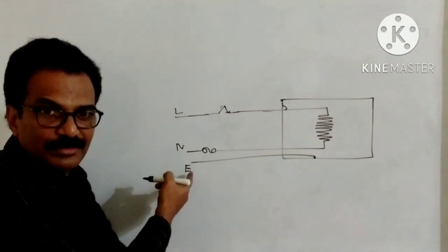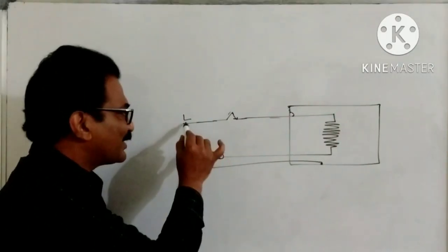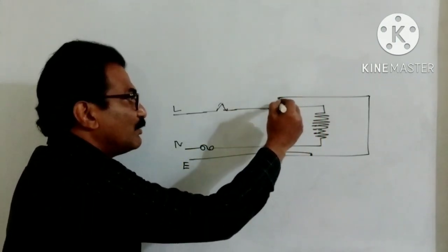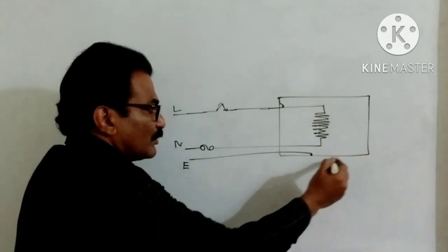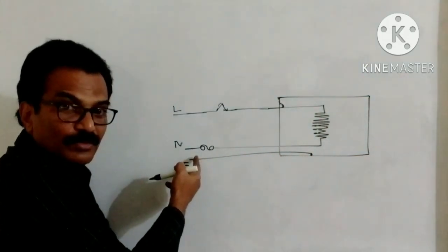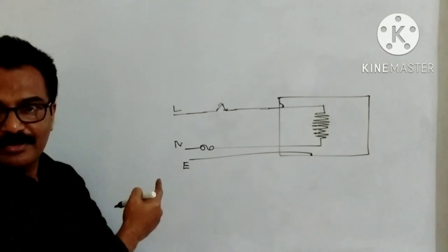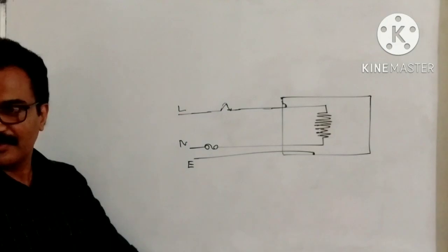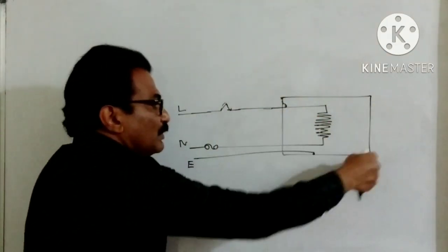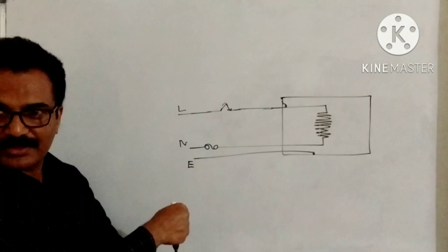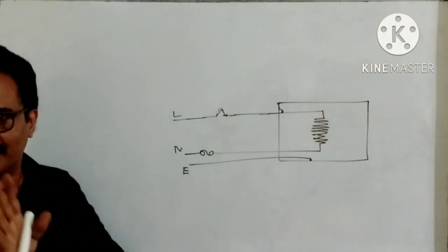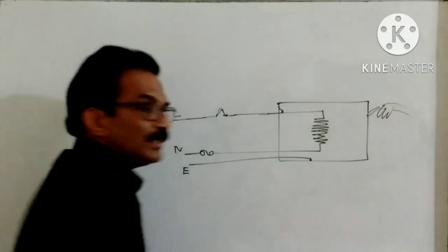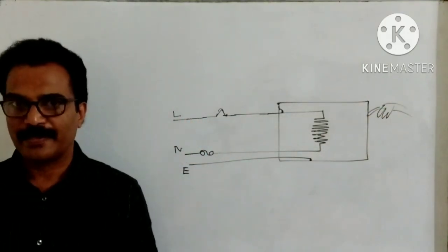Will the fuse melt? You do not listen to me. High current will not flow through this resistance. So here an easy path is there, no? So current will flow through this metal case. Will the fuse melt? No. Why? Because high current is not flowing through the fuse now. High current is getting another path. It will go like this, no? Fuse will not melt. This appliance will not be disconnected from higher potential, and the person who may touch this may get electric shock.